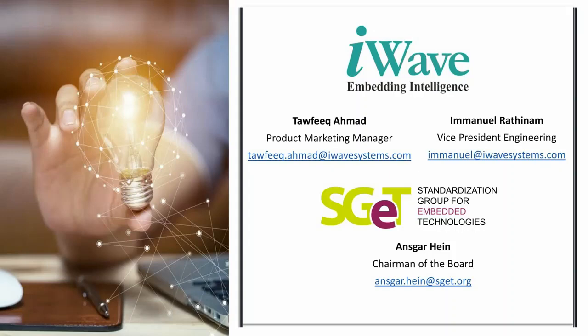So is it planned to release the 8M Plus OSM with automotive operating temperature? Right now, we do not have a plan, but we have the plan with the 8X Lite. The 8X Lite, from all the components, from all the perspectives, we are doing with a complete automotive grade. But 8M Plus, why we have not done it? Because the 8M Plus itself was made for AI kind of application. So we have not chosen the entire component portfolio with automotive, but definitely with minor component changes, it should be possible. If you have any specific requirement, you can discuss with us.